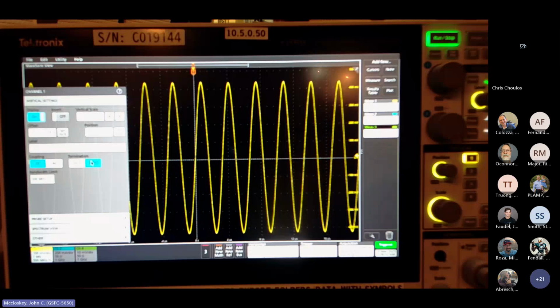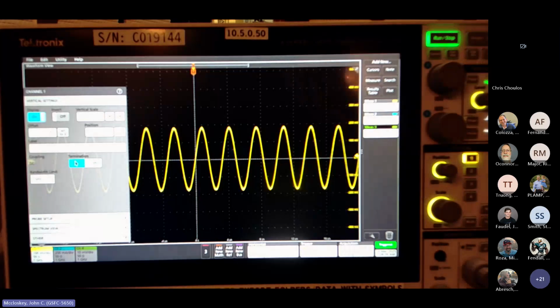And you're only tapping off of one of those 50 ohm loads. So at these higher frequencies, theoretically, you would expect the open circuit potential to be approaching a factor of 3 what you're seeing into that 50 ohm load. At the lower frequencies, the source impedance is much lower, so you're getting closer to the factor of 2. Anyway, I'm just going to stick with the 50 ohm load here to finish this out, and then we'll talk about what we're seeing.